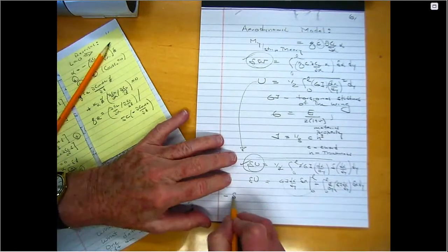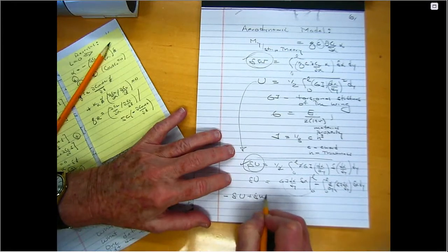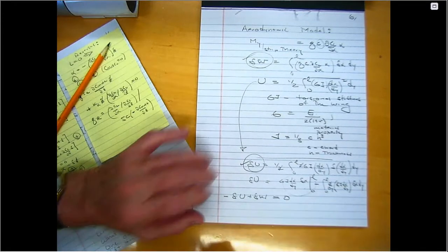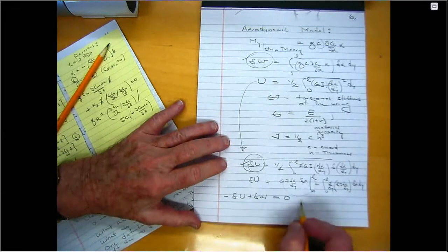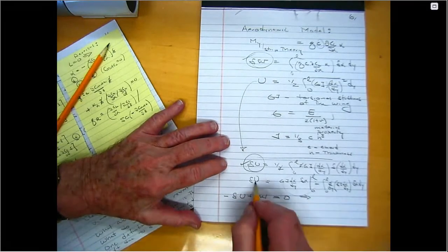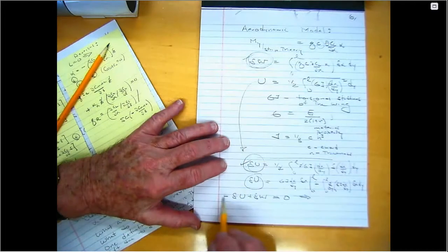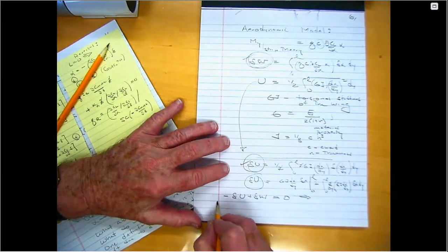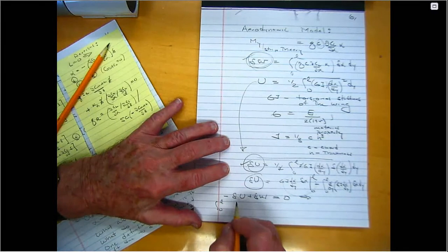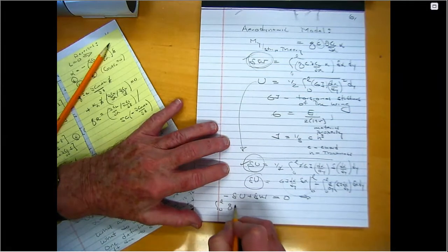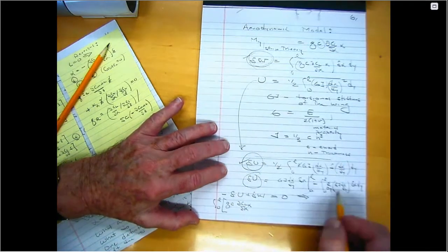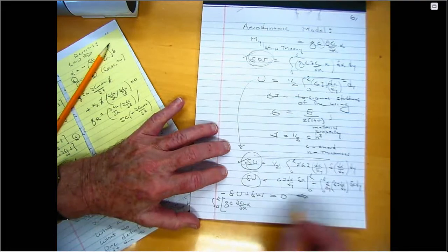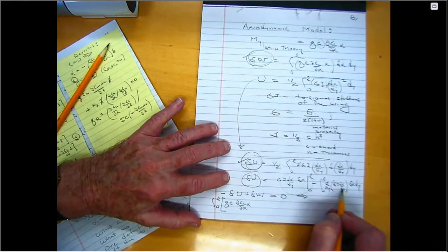We have minus del U plus del W equals 0. And what does that mean? If we write it all together, taking this expression for del U and this expression for del W, we're going to have the integral from 0 to L of Q C dCl d alpha times alpha. That's from del W, and it'll also be multiplied by del alpha in a moment. So they have this other term which also gets multiplied by del alpha.